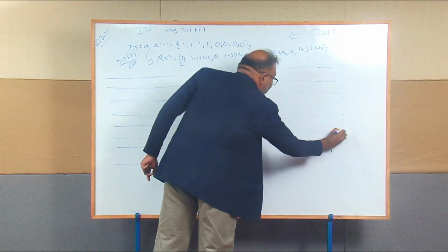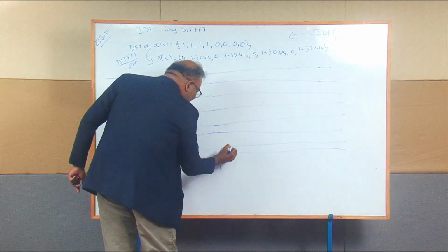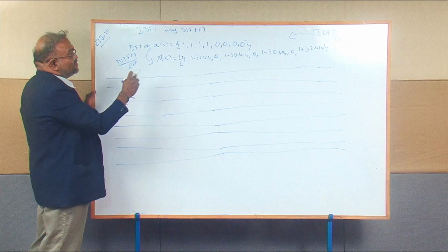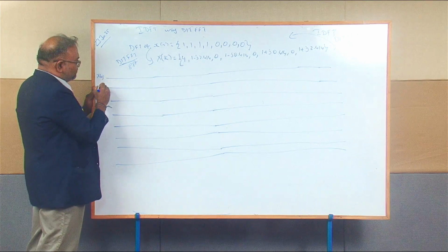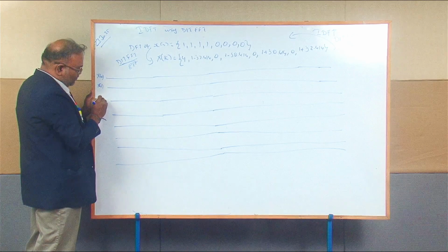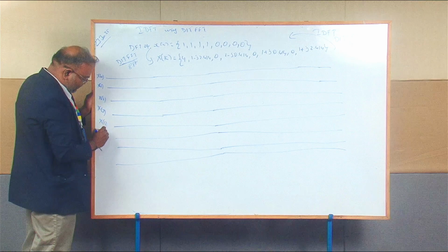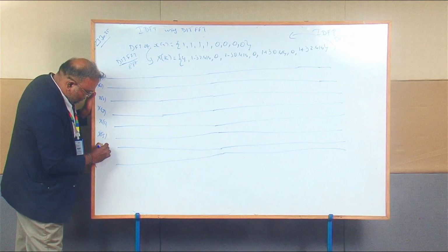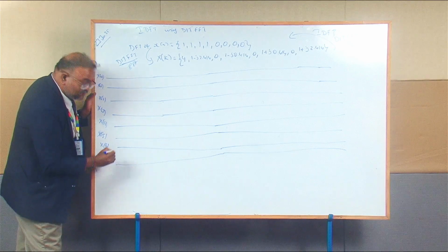The one more difference between IDFT and DFT is initially the calculation will be simple there, here little bit complicated. So decimation in frequency. So my input will be of correct order, x of 0, x of 1, x of 2, x of 3, x of 4, x of 5, x of 6 and x of 7.